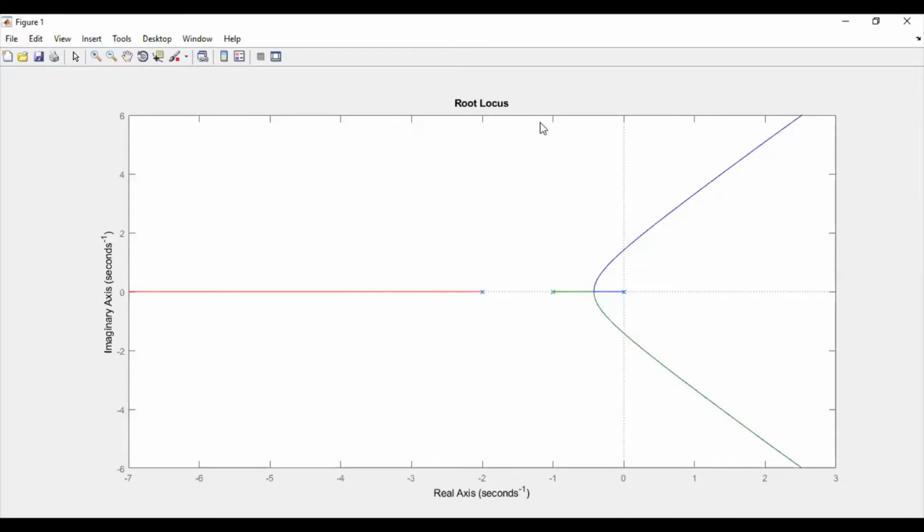So that's overlapping with the asymptote. That's why we didn't consider, right? Not overlapping with the asymptote, overlapping with one branch of the root locus with the other branch. That will never happen. Asymptotes are just lines. In this diagram, I cannot show the asymptote, but I will show you. We had drawn three asymptotes, dotted lines, one asymptote here. According to the definition of asymptote, it is just a straight line.